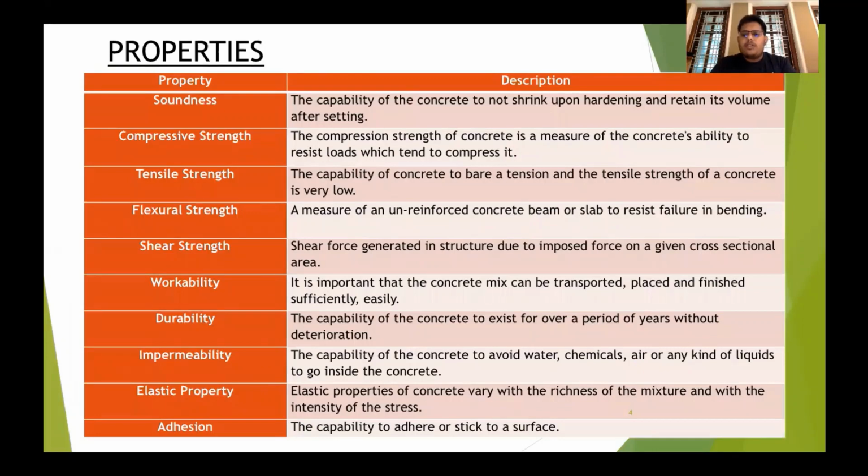Next, we are going to discuss the properties of concrete in this slide. Concrete is very high in compressive strength but has a low tensile strength. Concrete is durable, which will last for a long period of time, and also it is resistant to fire and other climate changes. Concrete has a capability to adhere or stick to a surface, which is known as adhesion. Some other properties of concrete are flexural strength, shear strength, workability, impermeability, and elasticity.